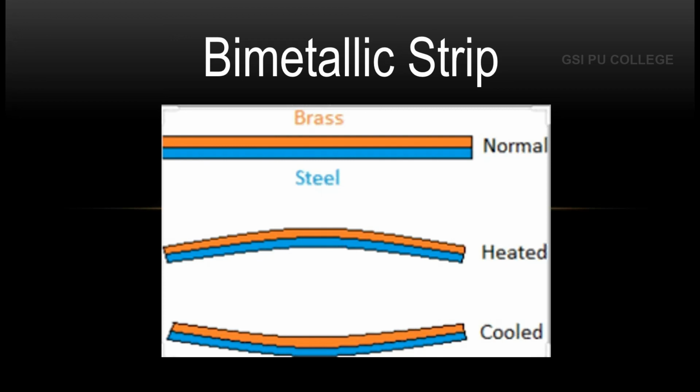mechanical displacement. The bimetal, where bi stands for two metal, is made up of two separate metal strips, a piece of brass bolted to a piece of steel or iron. Steel or iron expands less than brass as it gets hotter. So the bimetal strip curves inwards as temperature rises.